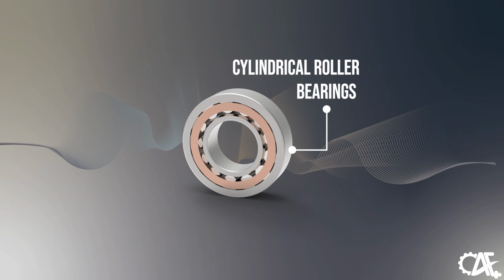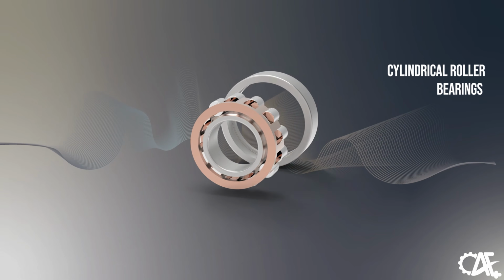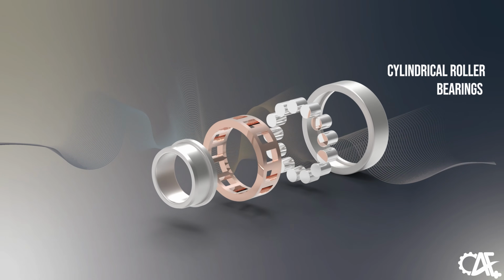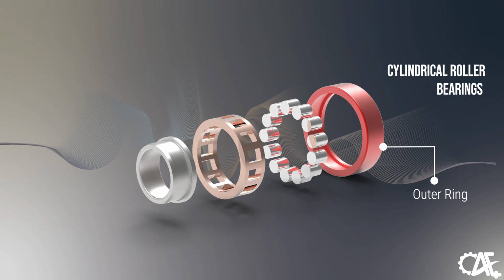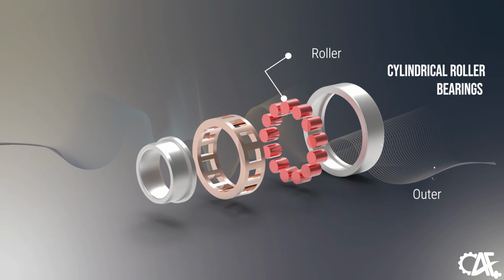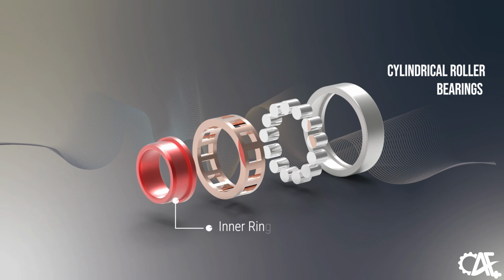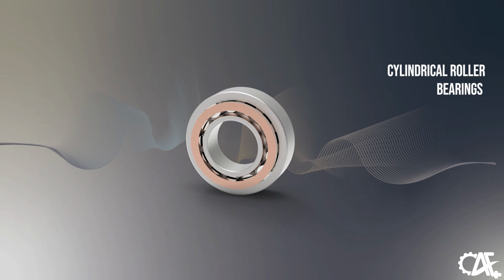Next up are cylindrical bearings. They feature cylindrical rollers for their rolling elements, allowing them to handle high radial loads. The rollers are guided by the ribs of the inner or outer rings. Without ribs, either the inner or outer ring can move axially. This makes them suitable as free side bearings, accommodating shaft expansion. With ribbed configurations, the bearing can effectively carry a minor axial load between the end of the rollers and the ribs. Moreover, they come in both single and double row designs, offering a diverse range of configurations.